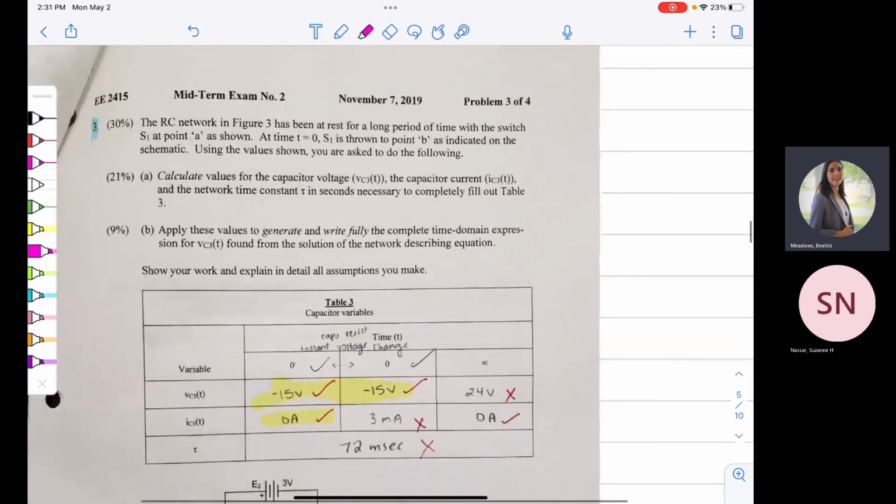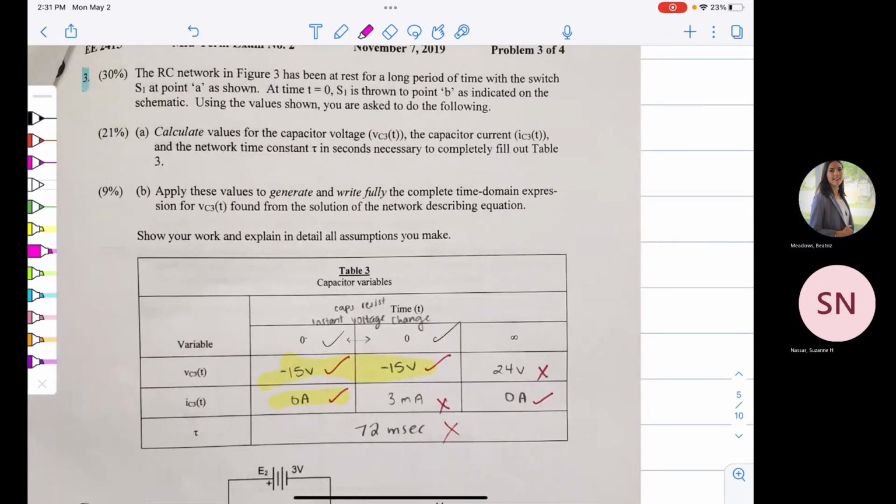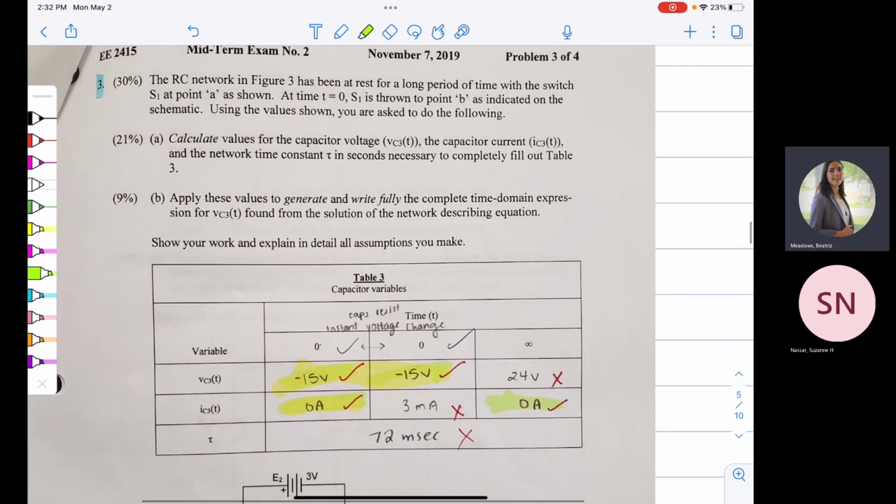And for your capacitor problem, your current is 0, not your voltage. Your current is 0 because you're in open, right? So it's going to be 0, 0 here, and whatever value you find for your voltage at 0 minus is going to be for 0 plus, okay? Was that your question? Yeah.